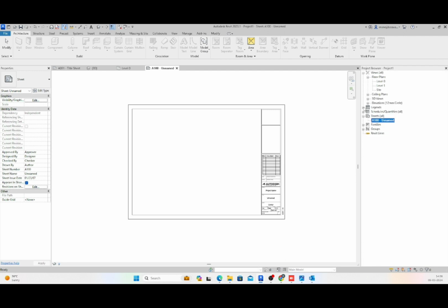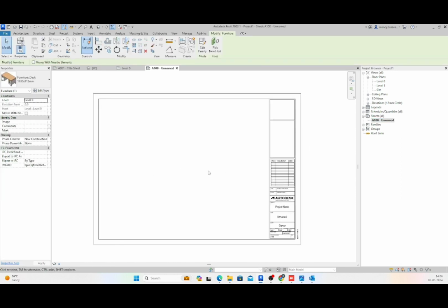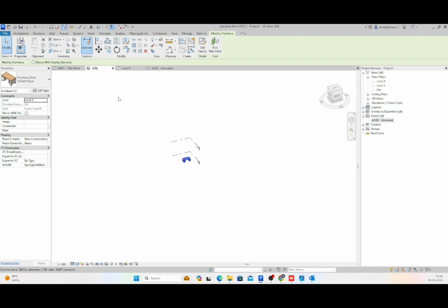And you can access the families, different groups, and other Revit links. From the bottom right corner, these commands help the selection tool, like do not select levels, do not select the pinned element. We will go through this topic as we move forward with the other course.